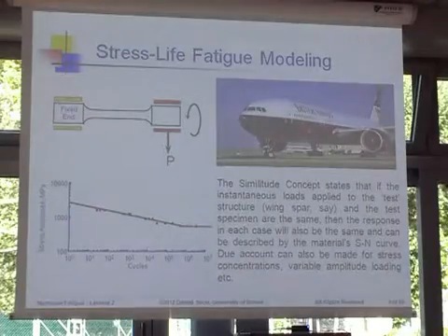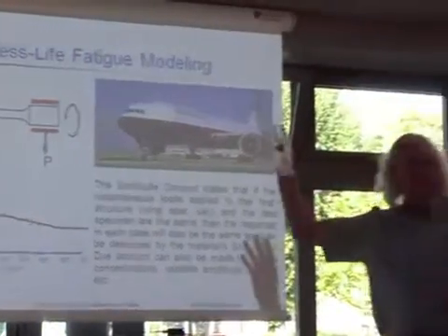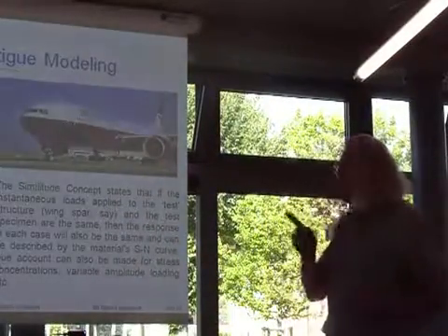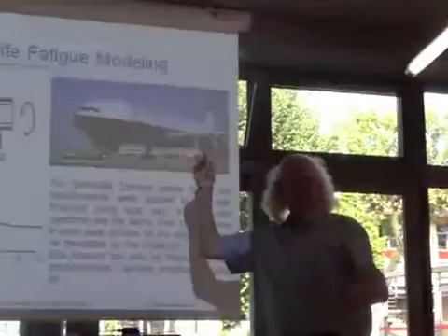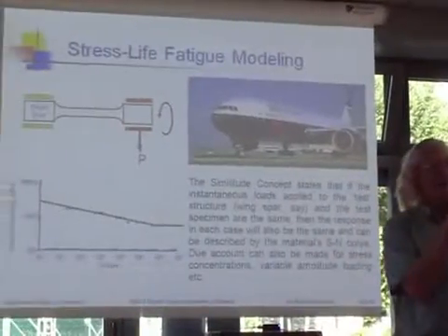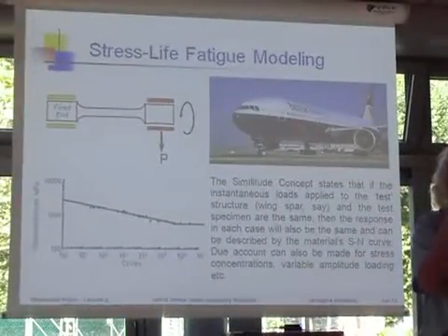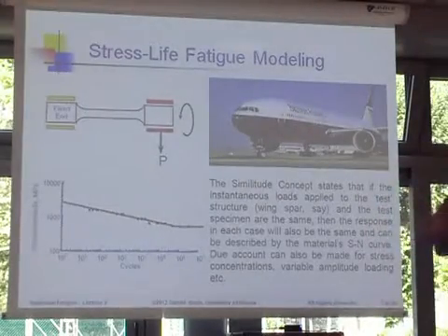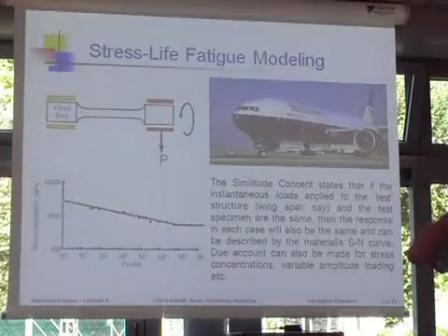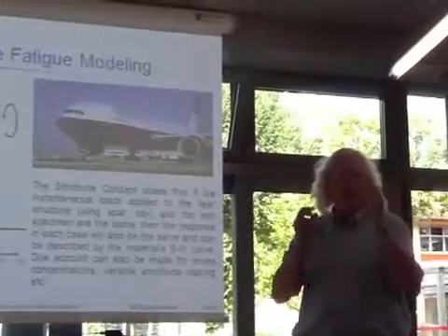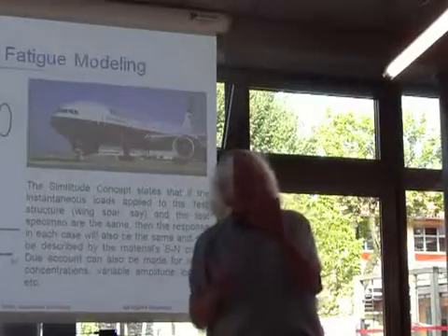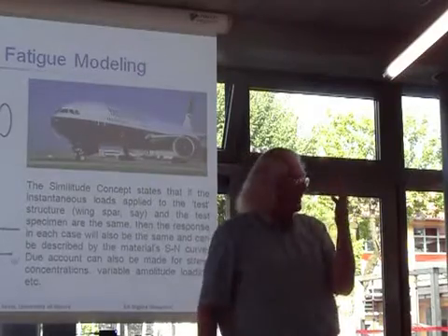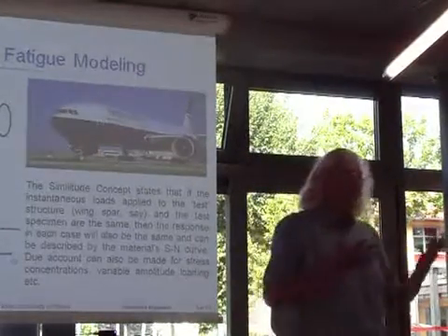So if you ask me anything about this airframe, then I would say this is horrible. But how about something that's actuating one of the flight surfaces? That's what you said. Look, where are the parts of the airplane that have to have a really long life? If I look at some steel part in here actuating one of the flight surfaces going up and down all day, it's probably a pretty good model. Because in order to have very long life, the physics is I have to be sure that the cracks don't nucleate. I have to keep them out. And keep them out, right?